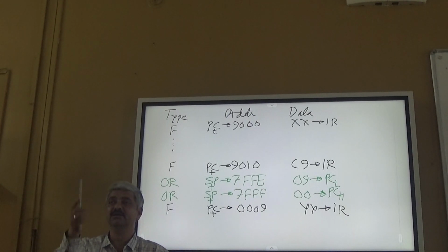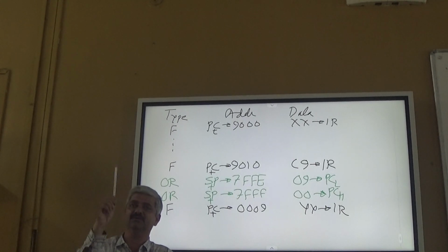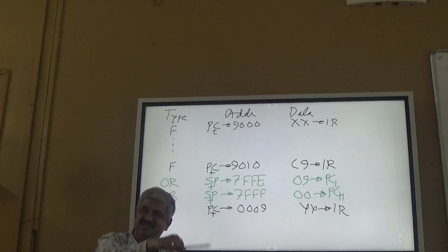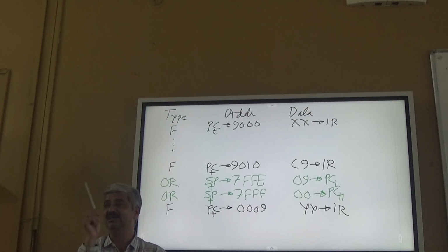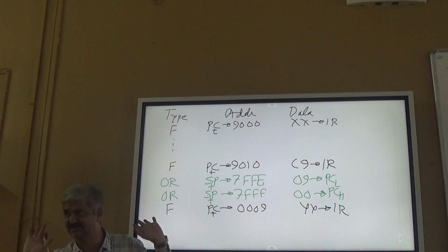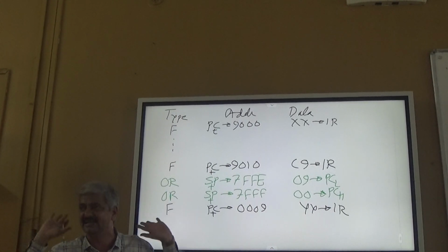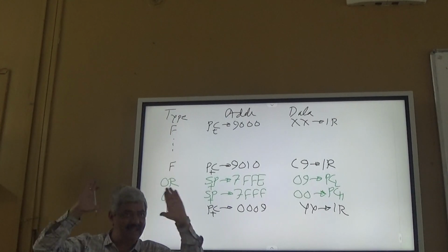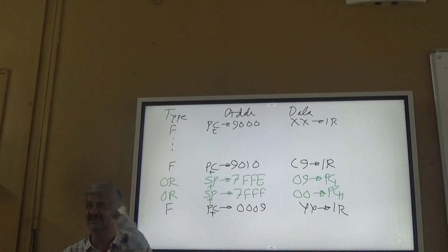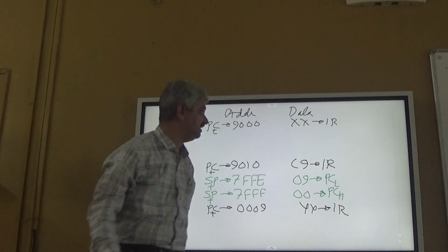So what I want is: the multiplication subroutine is supplied with the operands in HL, and it returns the result in HL. Other registers should not be changed. But with this strict condition of not changing other registers, I can't write the multiplication program. So I will take care that I will change them but I will restore them. At the end of the subroutine, all registers other than HL should be restored back if I want to use them.